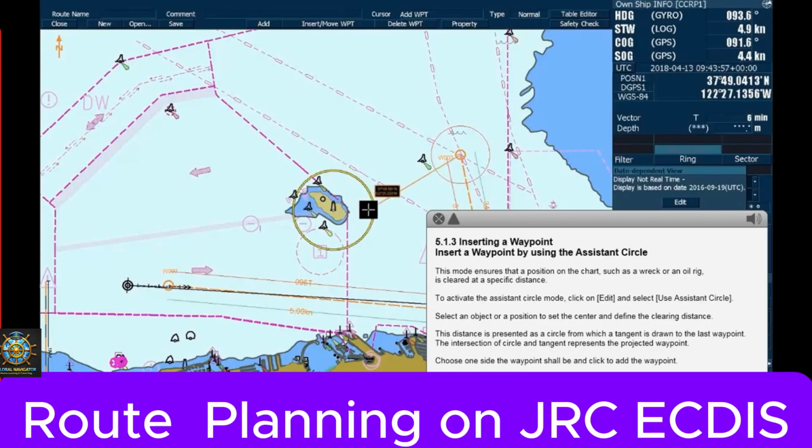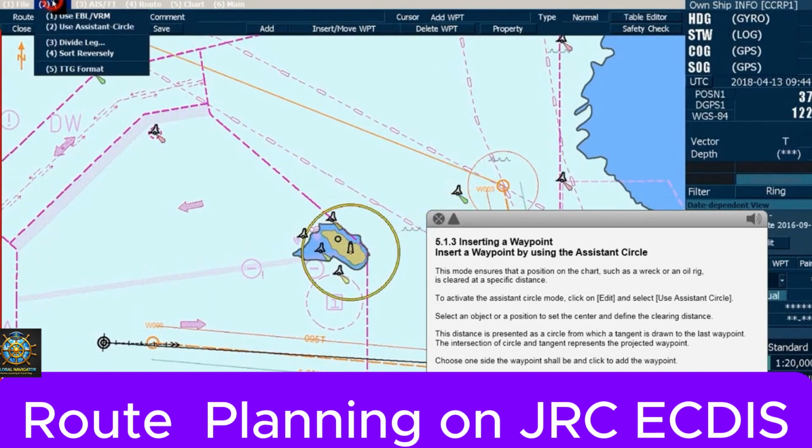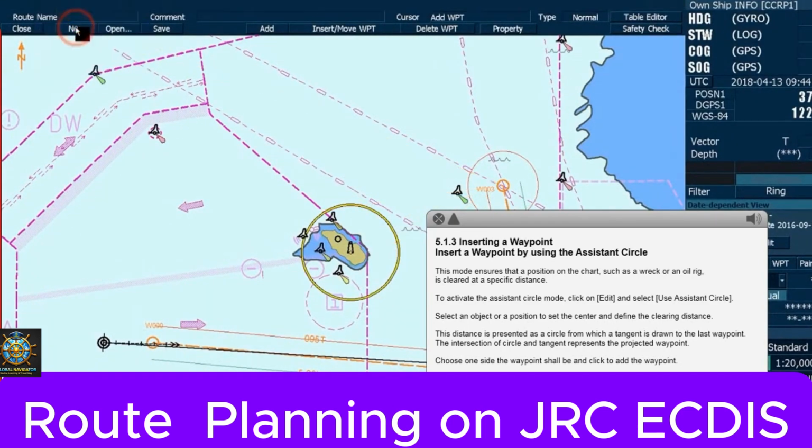Insert a waypoint by using the Assistant Circle. This mode ensures that a position on the chart, such as a wreck or an oil rig, is cleared at a specific distance. To activate the Assistant Circle mode, click on Edit and select Use Assistant Circle. Select an object or a position to set the center, and define the clearing distance.